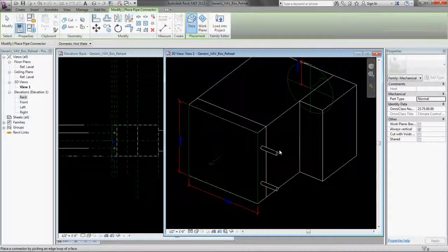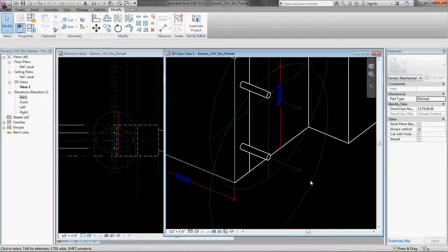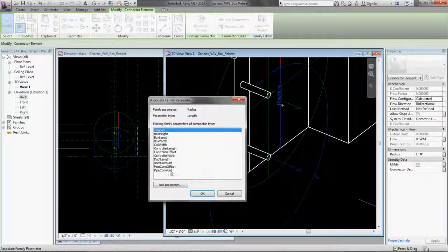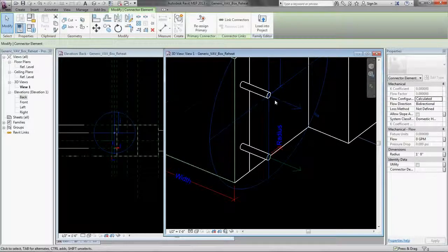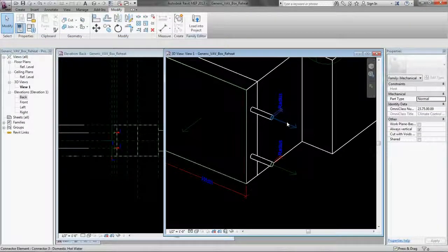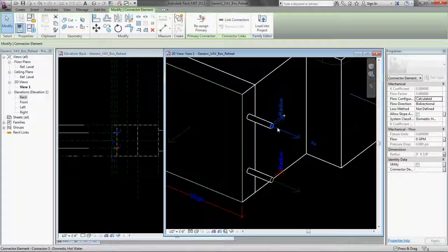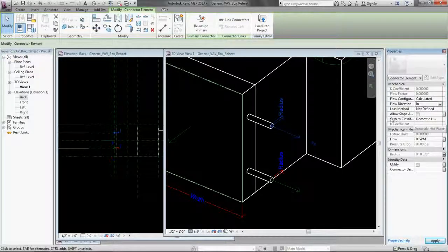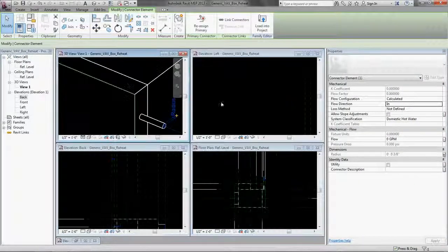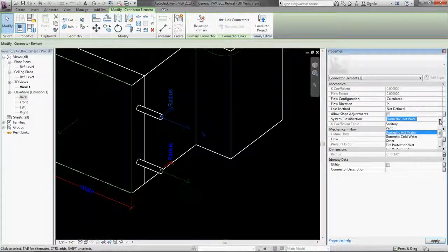The pipe connections are the exact same thing. Create pipe connector. Make sure you get the right guy selected. Set the radius. We'll set the top one to be inlet, so it's coming in. Let's take a better look. Nope, not domestic hot water. Hydronic supply.